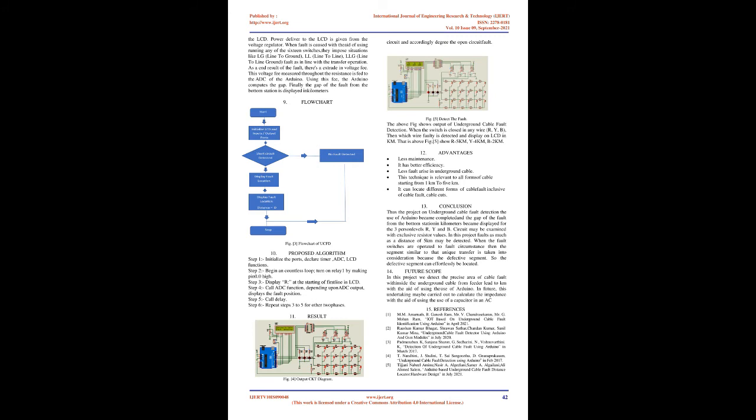Relay driver IC. A driver circuit is used to amplify or extend signals from microcontrollers to control power switches in semiconductor devices. Driver circuits perform functions that include isolating the controlled circuit and the power circuit, detecting malfunctions, storing and reporting failures to the controlled system, serving as a precaution against failure, reading sensor signals and generating auxiliary voltages. In this project, ULN2003 is used as the relay driver circuit. It is an integrated circuit which functions as the relay driver and boosts up the supply going to the relay circuit and thereby detects the open circuit fault.